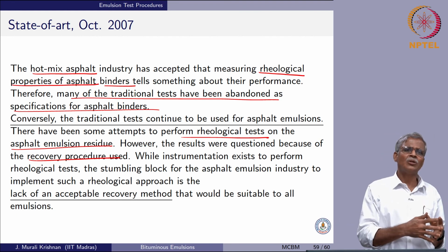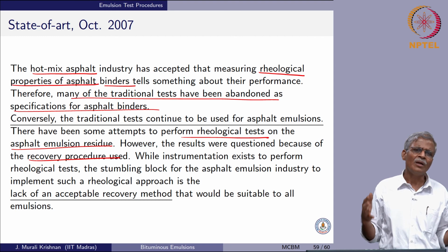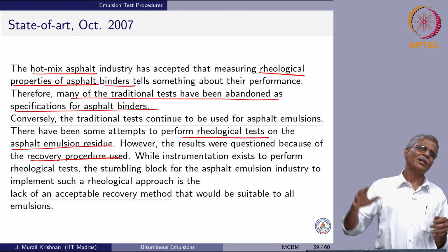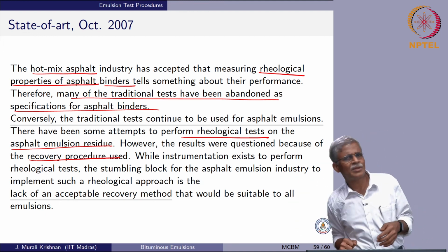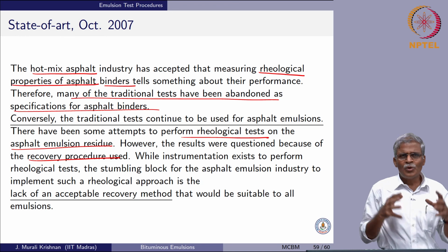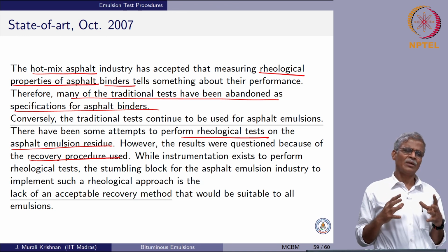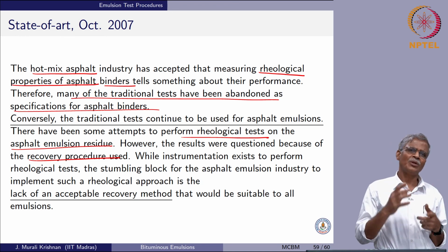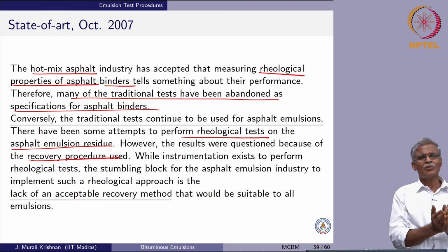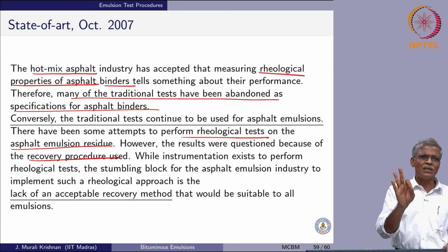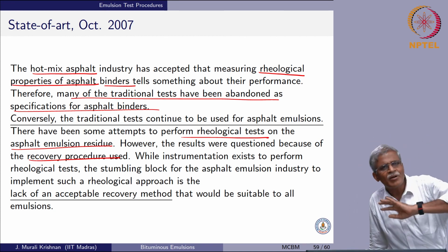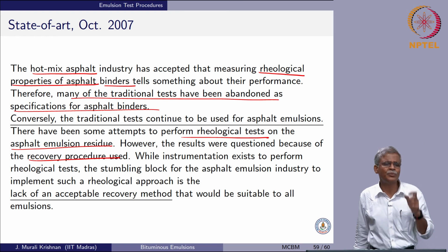You do a short term aging, you do a long term aging to find out what is the status of the binder after 7 to 8 years of service life, right. So, in RTFO, you more or less subject the binder to the changes that will happen to it during the mixing and compaction. So, the binder that you get in your lab after RTFO in a sense resembles the binder that is available in the field after the rolling operation is completed, right.